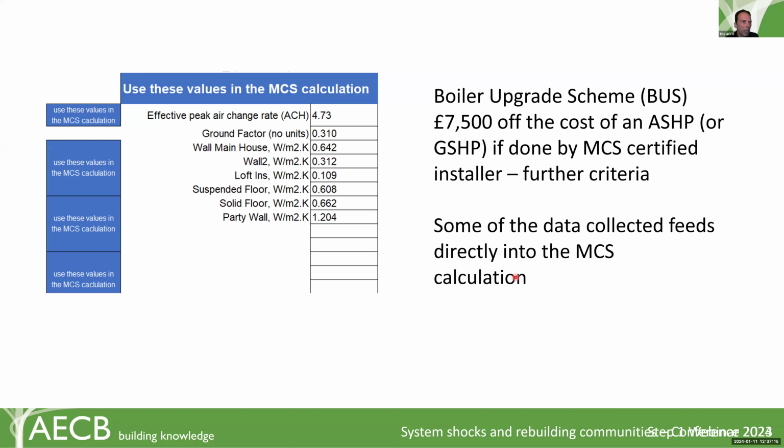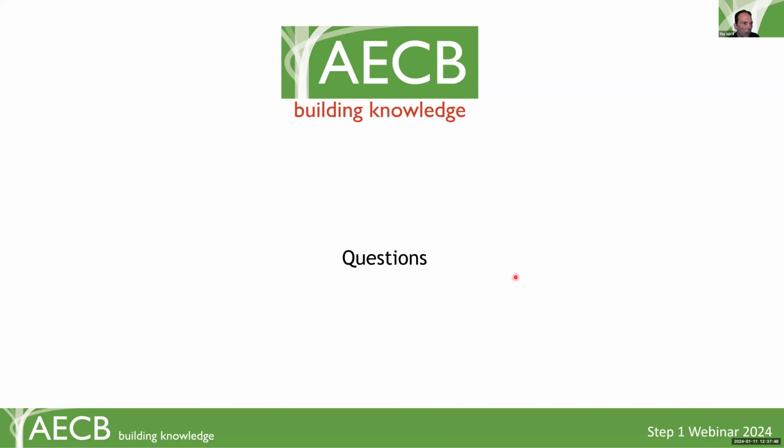And so the U values that were worked out in the building have been converted here. The ground one has to be converted so that it goes from normal PHPP criteria to include the ground factor, which is more part of the UK methodology for ground-based U values. So that's part of that as well. There's more information on that in the questions if you want to ask that.